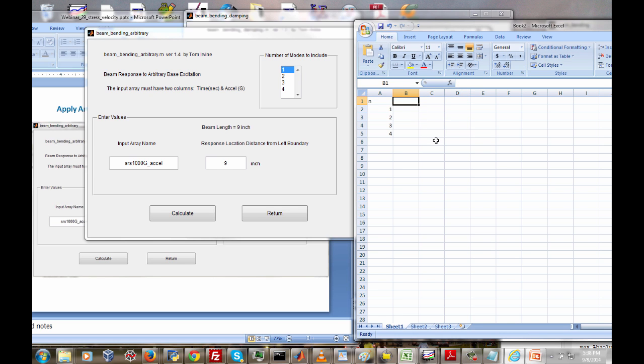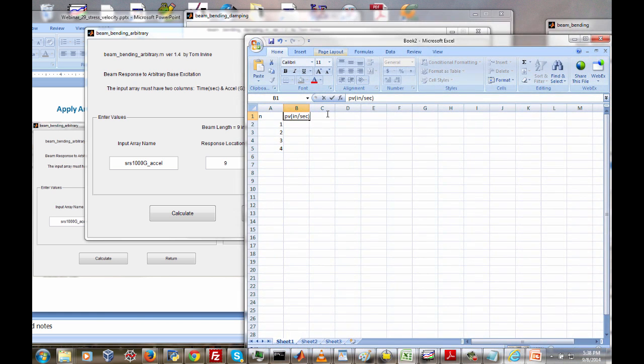And we're going to take a look at our pseudo velocity in inches per second. Now our pseudo velocity in inches per second is going to be at the free end. That's where the peak pseudo velocity is going to be. But our peak stress, our bending stress, is going to be at the fixed end. And it's going to be the von Mises stress. So I'm just going to say Vm psi.